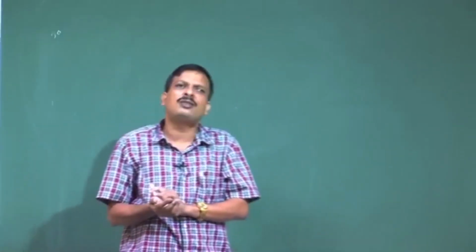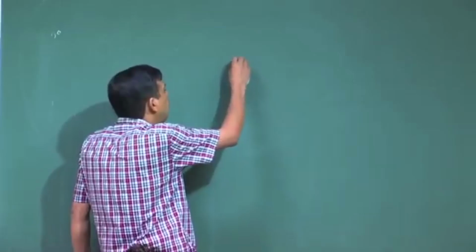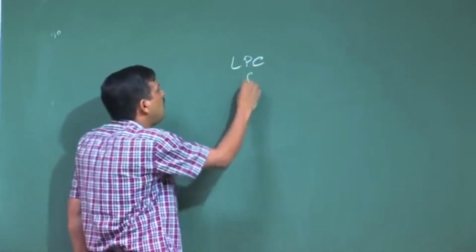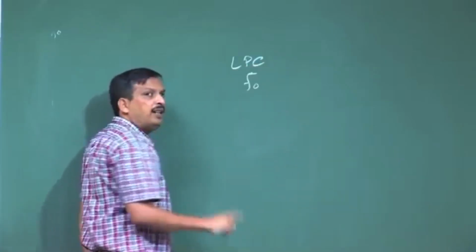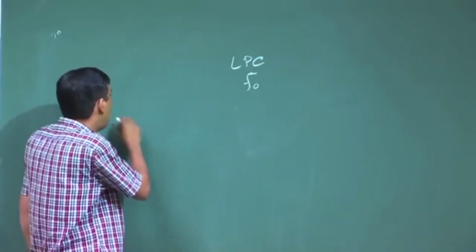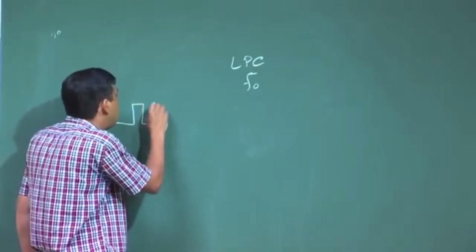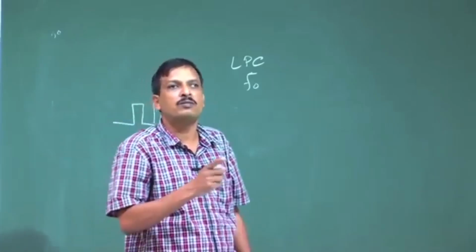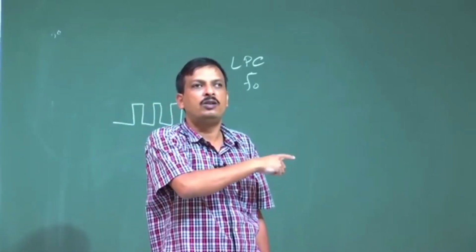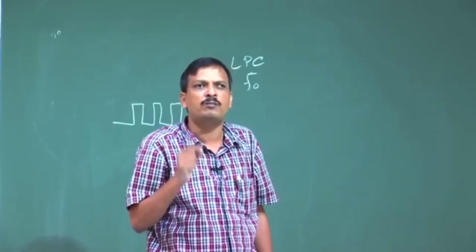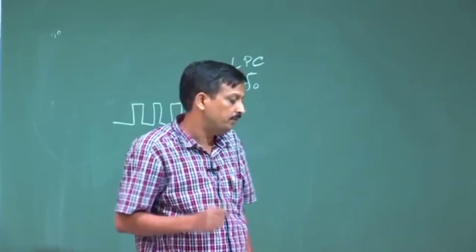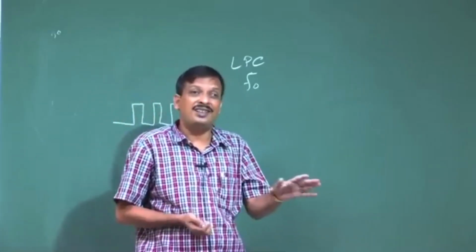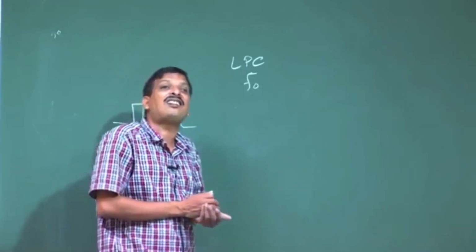Okay. Then speech coding, yes, already we have said that even in basic LPC encoding, F0 has to be provided at the receiver end, because I have to know what the F0 of the input impulse should be, which will generate that voice signal. So, F0 is a very important part of speech coding. Then voice conversion, very important. This is new technology, voice conversion, accent conversion.